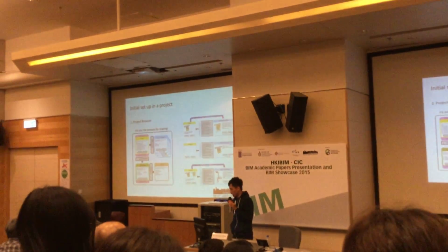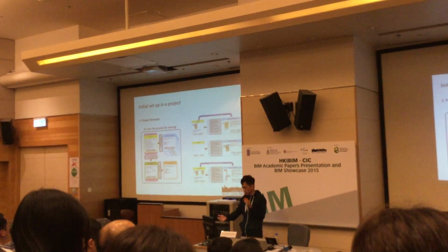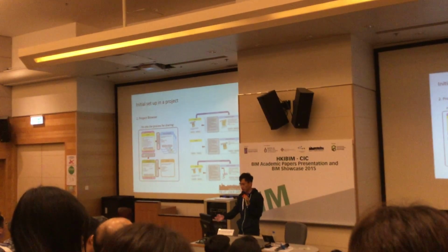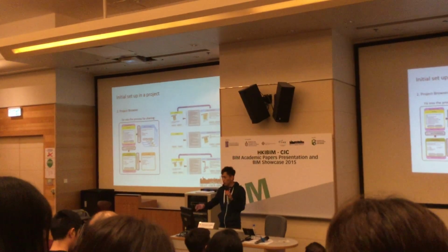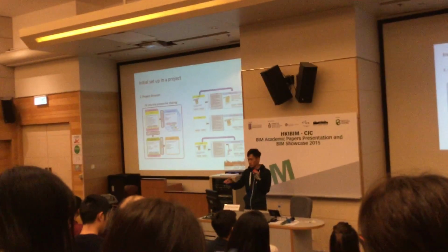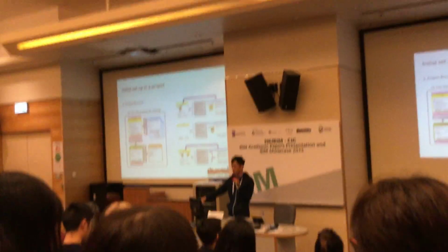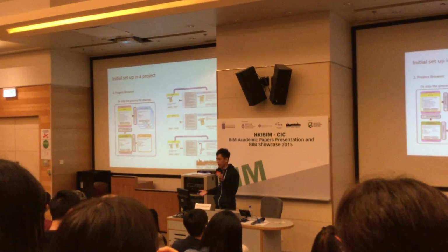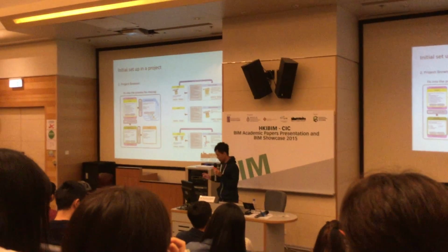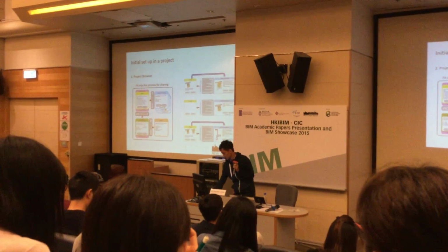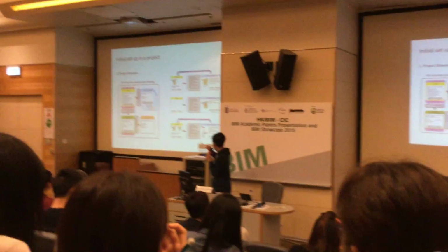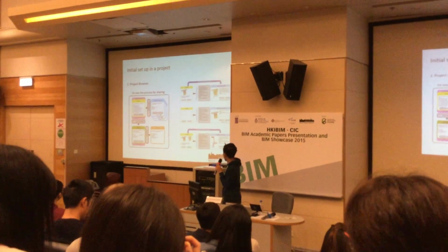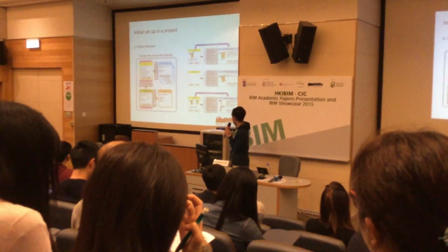And then you share to the architects and MEP and relevant parties. Because it's a coordination process, you go back to work in progress, for example after a meeting, when you've got changes or to avoid clashes. And I would say for the other disciplines, architect and MEP, it will be very similar.